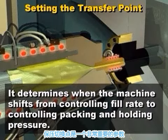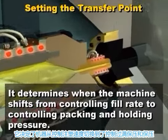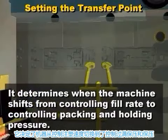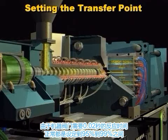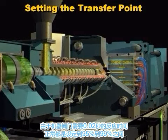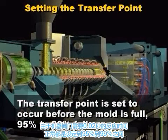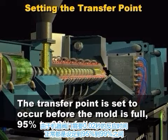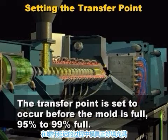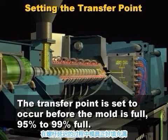The setting of the transfer, or cutoff point, is a very critical setting. It determines when the machine shifts from controlling the fill rate to controlling packing and holding pressure. Because the hydraulic valves take from 20 to 100 milliseconds to operate, the transfer point is usually set to occur just before the mold is full, typically at 95 to 99% full. During the delayed hydraulic valve response, the cavity completes filling.